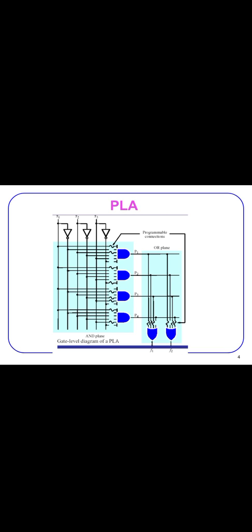The product terms present in the Boolean expressions are for the X and Y conditions. One product term, AC, is common in every equation, so the total logic gates for generating these two functions are four AND gates and two OR gates in the programmable device.